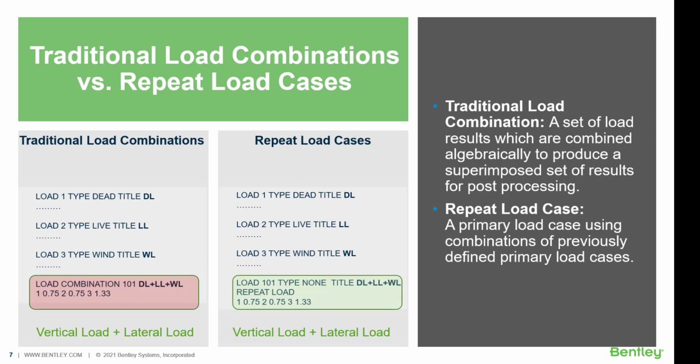Therefore, traditional load combination should be used in a linear elastic analysis only. In a buckling analysis, one would need to create new primary loads that combine basic primary loads. This is made easier using the repeat load command.